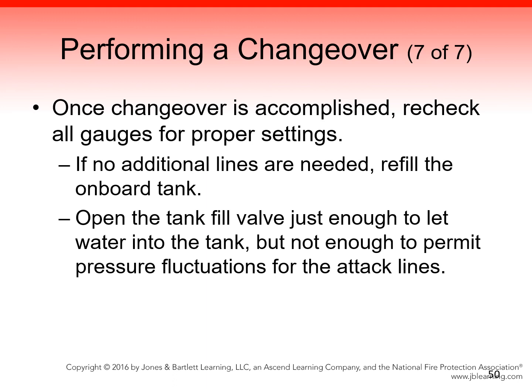If no other additional lines are required for pumping, now is a good time to refill the onboard tank. Slowly open the tank fill valve to allow water to refill the tank. The tank fill valve should be open just enough to let water into the tank, but not enough to permit fluctuations of pressure for the attack lines. Follow the steps in Skill Drill 11-4 to perform a changeover operation. Always refer to and follow the manufacturer's recommendations for your department-specific apparatus.